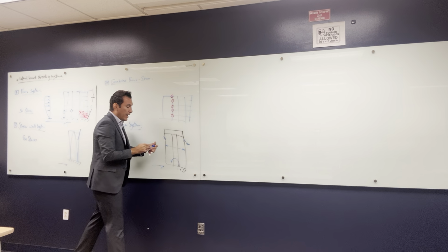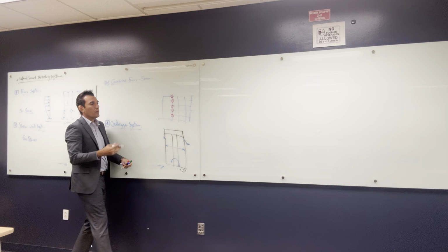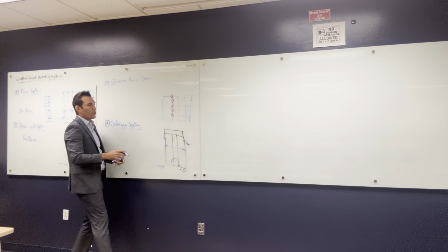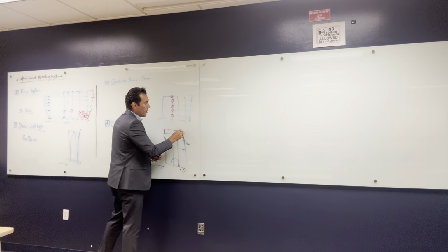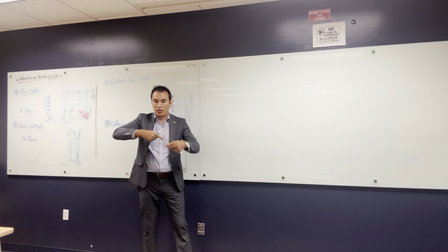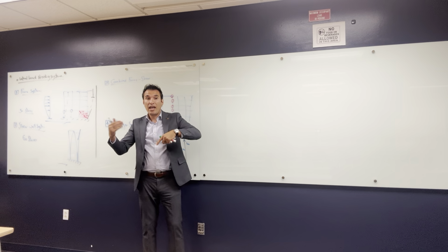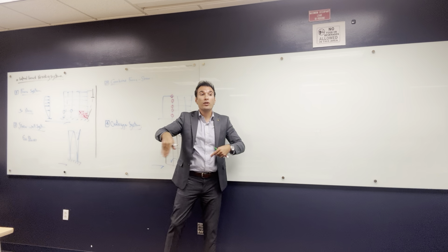And if you want to enhance this outrigger system, you can do multiple things. If you guys remember last time, there was a belt around the building, like you make the whole outrigger surrounding the whole story, and you make the outrigger distributed.